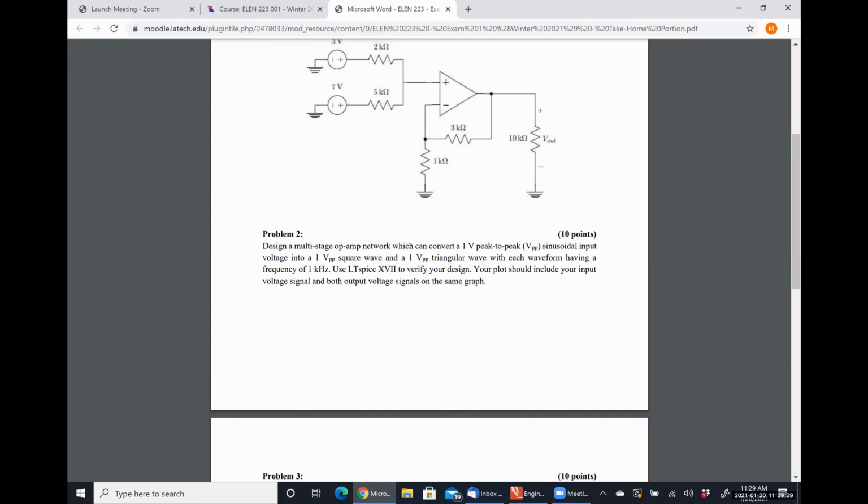So if I want, I believe I say I want a frequency of 1 kilohertz, that's going to inform your decision on what size of resistor and capacitor to use, because you need RC, the product of R and C, to be on the order of 1 millisecond, I believe, with a 1 kilohertz frequency. If you have it too short, so if you size your components incorrectly, you're never going to fully charge or discharge, and so you're going to see that it constantly kind of builds up and looks weird.